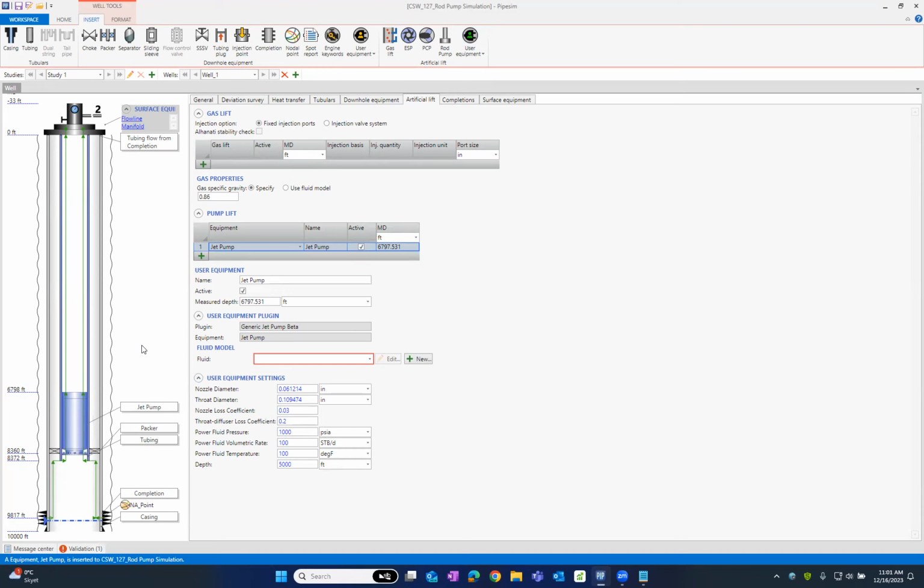This one is also affecting the density, but the main mechanism is reducing the pressure due to the very high velocity across this pump. As you can see here, there is a nozzle that makes the fluid passing through this pump very high velocity, and due to that very high velocity, the pressure will be less.